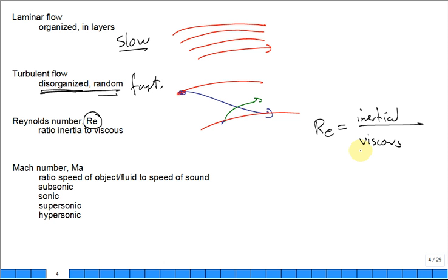And we'll talk more about viscous, but a packet by itself, really, you don't talk about viscous forces, you talk about adjacent packets of fluid. So if one fluid's trying to go fast and its neighbors are all going slow, the neighbors have a retarding effect, pulling back on the fast packet. And the fast packets pull on the slow packets of neighboring fluids to move them forward through viscosity, viscous effects.